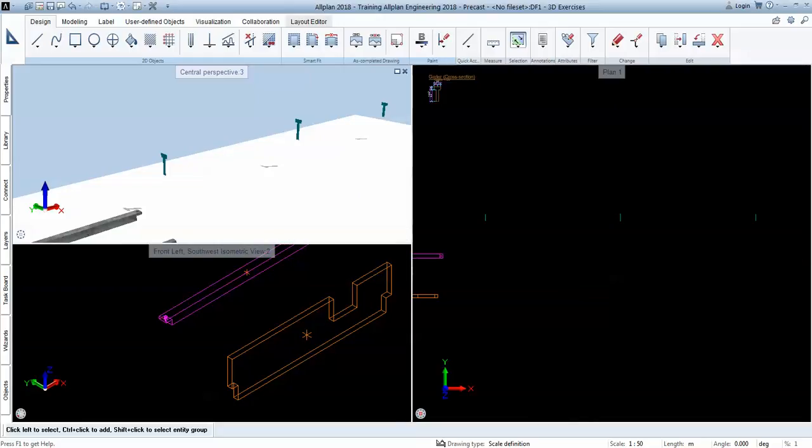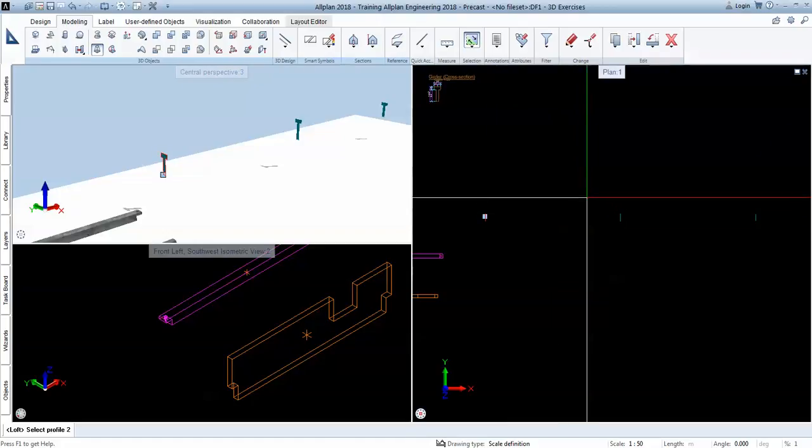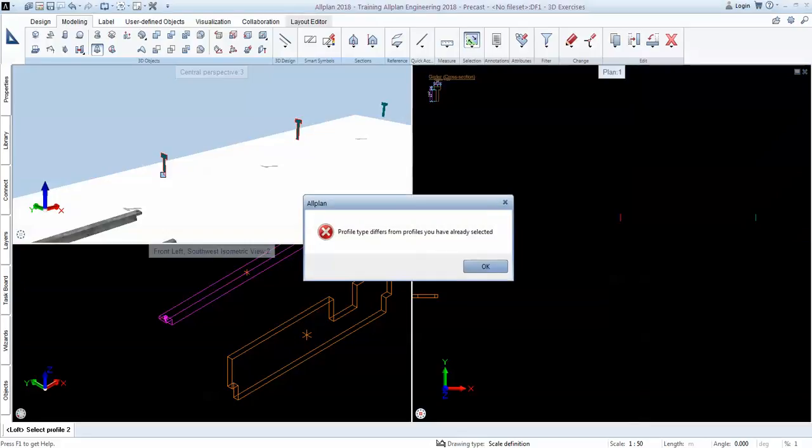So from these 3D sections, to create a 3D model out of them, so this variable cross section, all you need to use is this Loft function, which can be found here in the modeling Loft. And Loft is a function that interpolates in between cross sections. So it will guess a way to create the variation. I'm selecting the first section, then it says on the lower left side select second profile.